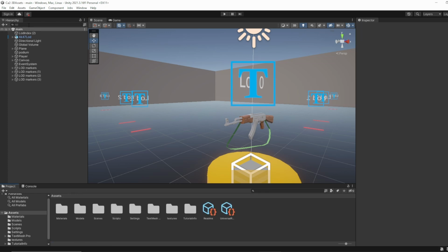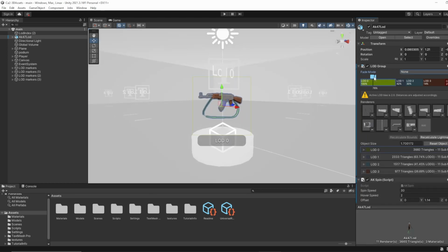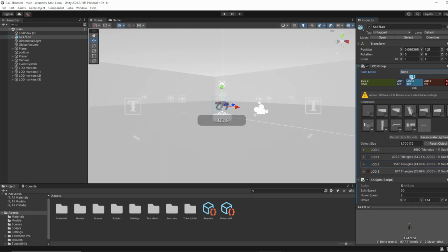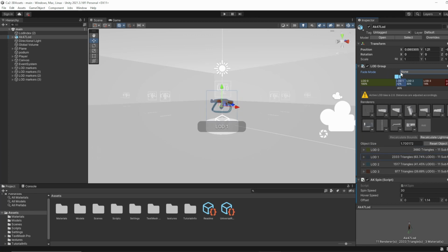The next thing I had to set up was the LOD groups. The way you can set that up easily is by going to Add Component, LOD Group, and once you click LOD Group it'll give you this kind of thing. So you can adjust the camera here and have a look at the different distances when stuff changes. As you can see, the little meshes change.